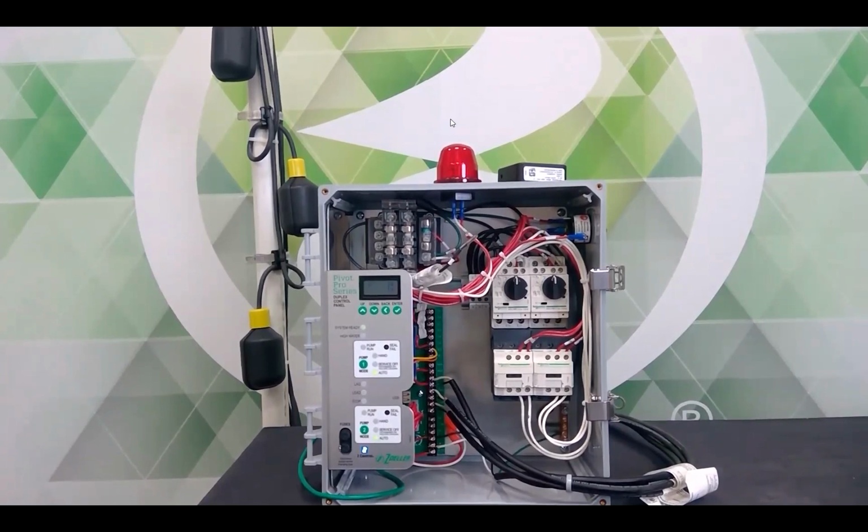And all you have to do is get into the menu, and there's a spot where you see ratio and you just change the numbers. By default, it's 1-to-1, and you change it to whatever you want. And those of you that are thinking through that a little bit might realize what that means. That means you don't need a lead lag selector switch anymore. You don't have to option that out in your panel. It's built right in. Not only can you do a lead lag setup, but now your lead pump, which is running all the time, say you have it set 99-to-1, your lag pump gets an exercise cycle once every 100 cycles instead of just sitting there dormant forever. So all of this has been thought through. It's all built in.